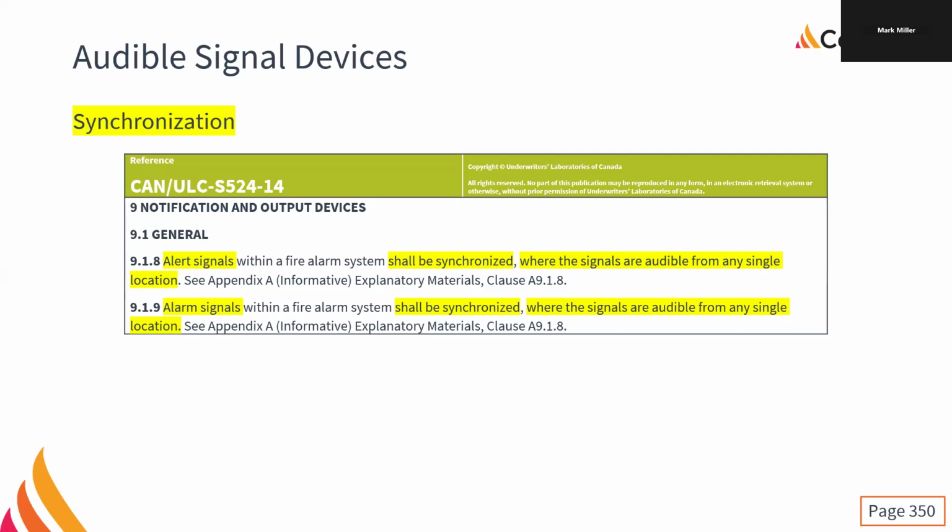Synchronization with Mircom can be annoying to get it right and get it sorted. I've seen techs struggle for hours to get synchronization correctly. I've never seen a Simplex technician do anything to get the synchronization correctly, except for turn on the checkbox to tell it to synchronize in the programming, and that's it. So I've seen it not synchronize, and the tech goes, "Oh, I forgot to synchronize it." Just hits the check and then re-downloads, and off you go. But it has to be synchronized.